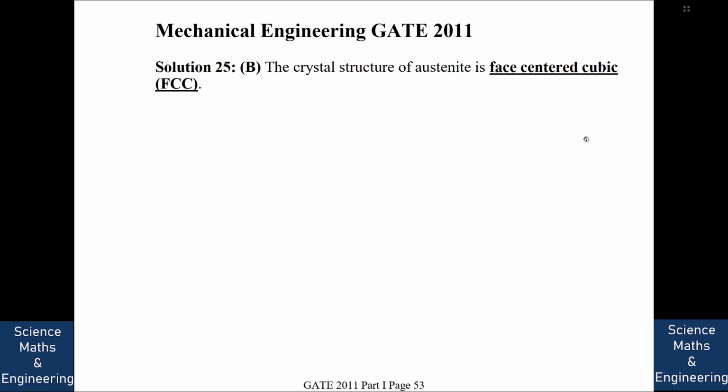There are others like martensite and some other crystal structures. So all have different structures and they have different properties. So that is why we try to understand the iron carbon diagram very carefully, and we use this iron carbon diagram to attain specific hardness or ductility based on the requirement.